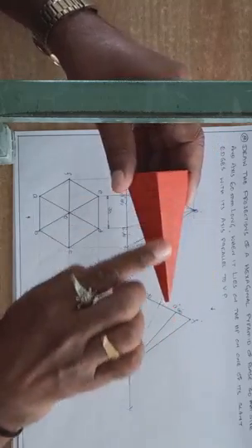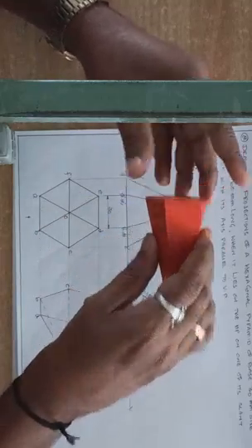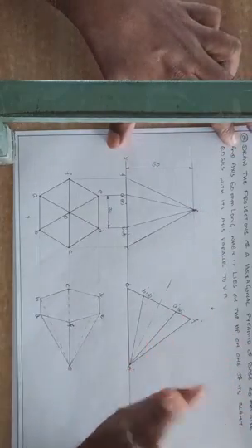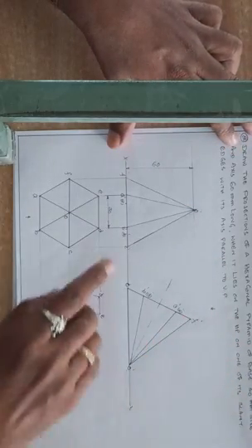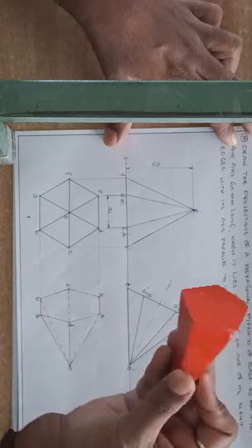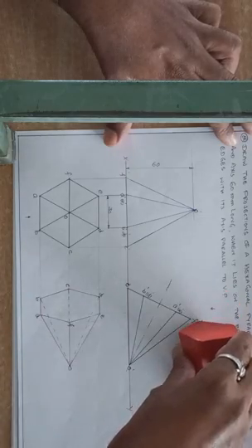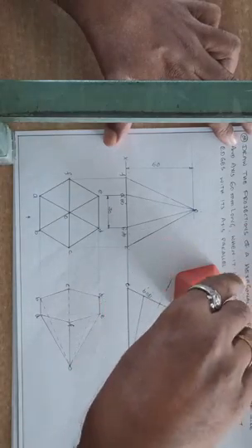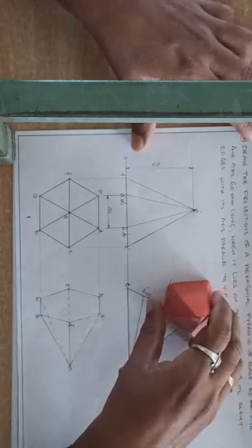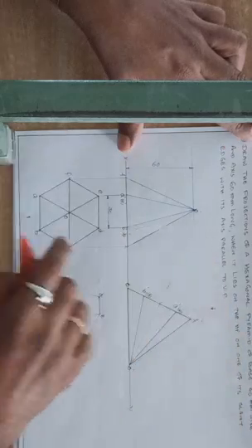This corner is the slant edge. So this is the slant face. Okay, be careful. Now, slant edge with its axis parallel to VP. So here also, before resting with its slant edge, this edge is perpendicular to HP. Therefore, the true shape is obtained in the top view.